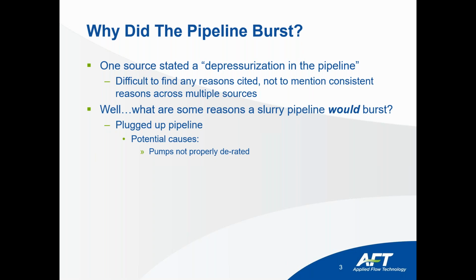The effect of solids on the pump is going to be significant, and it will decrease the amount of added pressure and flow from what you would actually be expecting. If you're expecting a certain flow and pressure based upon the clear fluid, you're not going to get the same when you're actually pumping the slurry. So it's important to make sure that you properly derate your pumps, so that you have a powerful enough pump that can do the job for you.